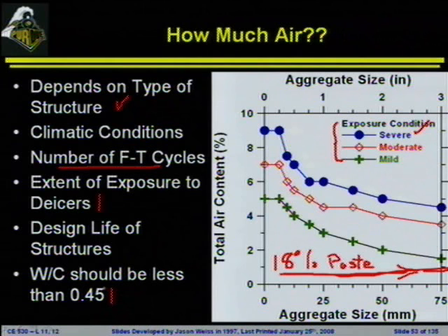And the water-to-cement ratio is going to be related here for 2 main reasons. One is because the water-to-cement ratio is going to be incredibly important for the strength of the paste itself. And the second thing is the water-to-cement ratio is going to dictate the permeability of the paste. And as we change the permeability, what we're going to be changing is how fast the water is entering that concrete. So we're changing its likelihood to saturate.